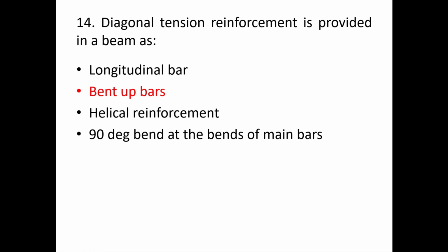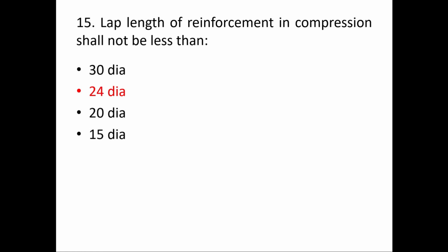Okay. So move on to the last question of this video. Lap length of reinforcement in compression shall not be less than. So again, from Indian standards, we know the lap length in compression shall not be less than 24 times the diameter of the bar. Okay. And for lap length in flexural tension, it shall be greater of 30 times the diameter of bar or the development length. Okay. So whichever is greater. For flexural tension, it is 30 times the diameter of the bar or development length, whichever is greater.